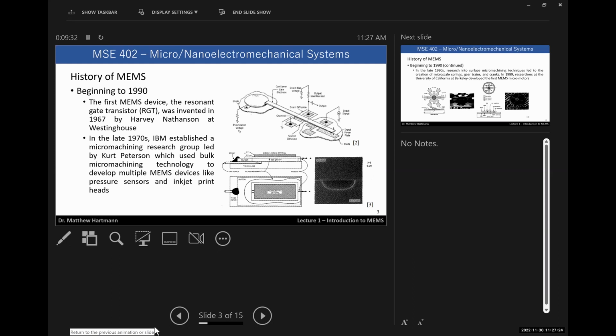So for this particular device, if you apply a voltage across the piezoelectric crystal, depending on the polarity of that voltage, the crystal will either expand slightly or shrink slightly. You would apply a voltage which would cause it to expand. The expansion of that piezoelectric crystal will cause this diaphragm to deflect downward, putting pressure on the ink cavity, which squeezes the drop of ink out of this needle effectively, right? So that's how you squirt ink out.